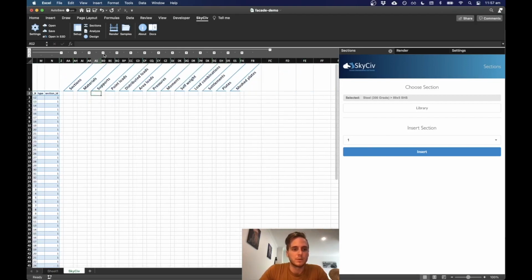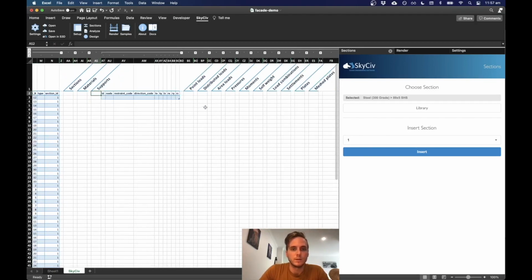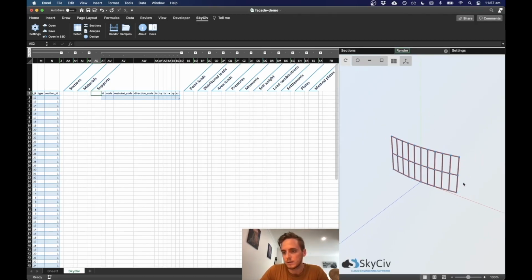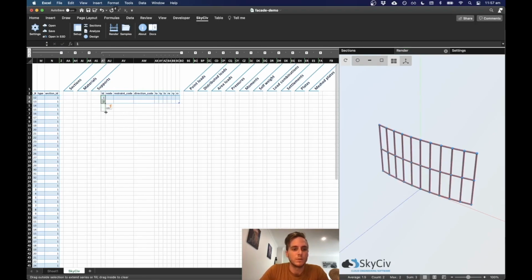If we come to supports, we're going to need to add in a few supports. We'll look at adding one here, here, here, and the same on the other side. So we'll have 6 supports, and we need to work out what those node IDs are. We know our first one was 1, and then we went over to 11 on the other end. So that means the next one will be 12, and then the next one will be 22, and then 23 and 33.